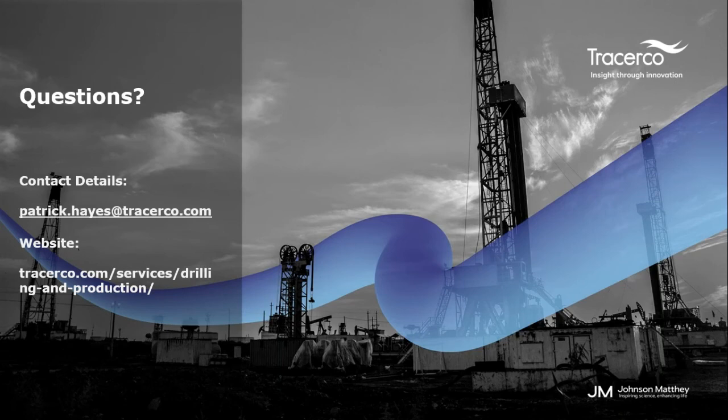A lot of the things that can skew your analysis of these sort of flow quantifications come from bad pre-planning. So when tracers are used that, for example, aren't thermally stable, and you start seeing degradation in the reservoir itself, that can obviously throw off your quantification efforts. And so a good vendor ought to do a fair amount of pre-evaluation to show, hey, my chosen tracers are in fact thermally stable for an extended period of time, and can provide that sort of data to you.